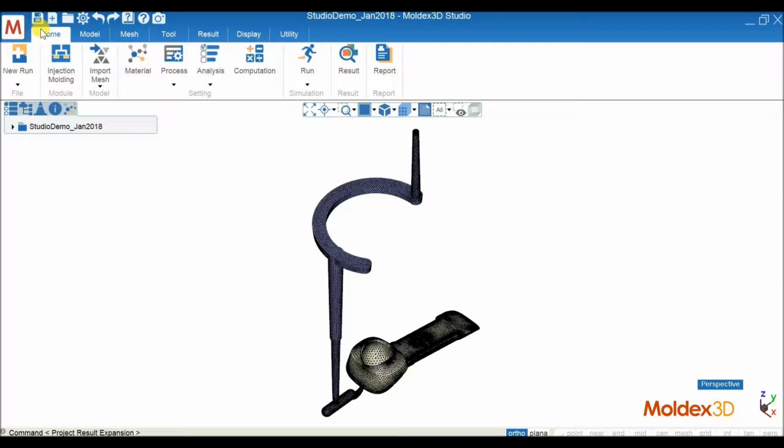So as you can see in this case, we use a one-shot injection molding, and the background for this case is that in this ball socket we have a thickness, so we will encounter problems like a sink mark, and also for this part they demand to have a cosmetic surface. So like weld line, we must eliminate the weld line.